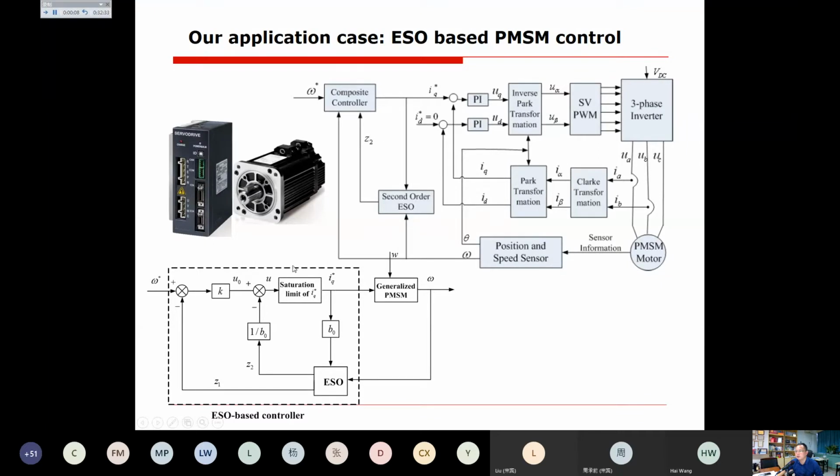We successfully used the disturbance observer-based control method, which we called the extended state observer-based control method. Previously they used PI, also called piecewise PI or intelligent PI, in a servo driver in the speed loop. Then we changed it to P plus disturbance observer, P plus disturbance compensation, not PI. And now they use this in different types of servo drivers.